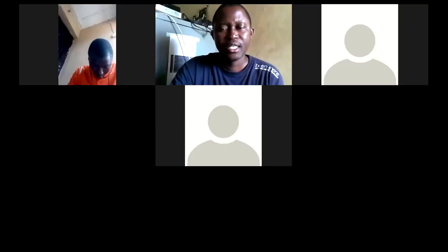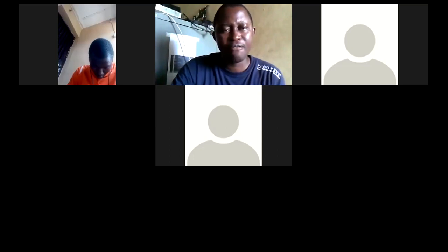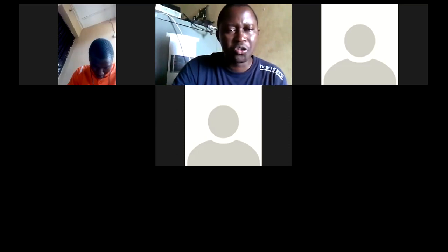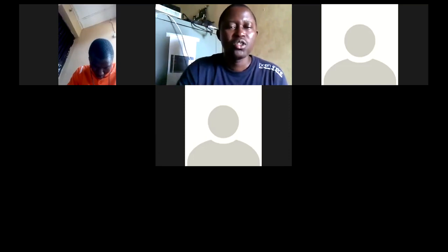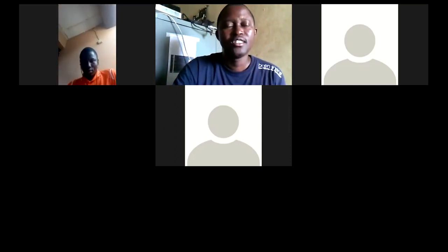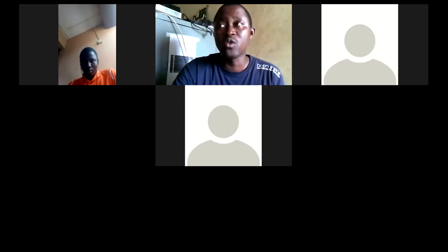Now let's look at the second one, F2 prime. Let's look at the effect of the feedback on F2 prime. F2 prime equals F2 multiplied by 1 plus beta A. Remember, 1 plus beta A is always greater than 1 because beta A, no matter how small it is, you can have it as 0.001, 0.1, whatever, it's always greater than 0.